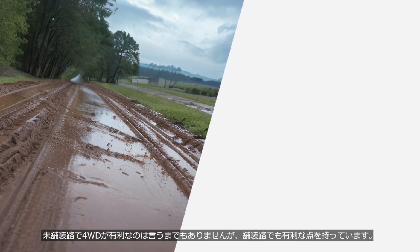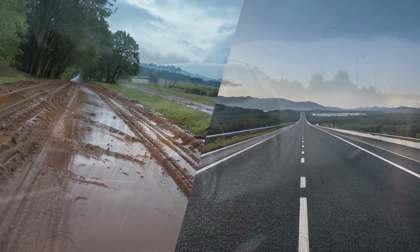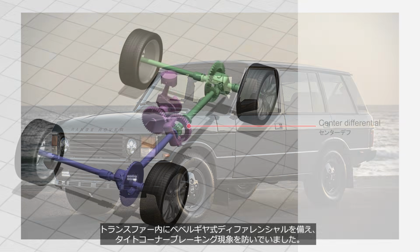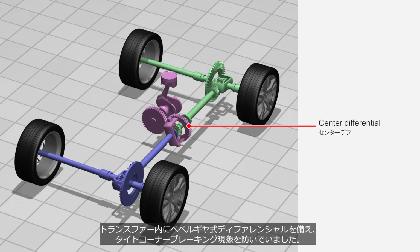While AWD is obviously advantageous on unpaved roads, it also offers advantages on paved roads. It improves straight-line stability at high speeds, and enhances stability during acceleration when the road surface becomes slippery, even on paved roads such as in rainy conditions. The first mass-produced passenger vehicle to adopt full-time AWD was the first-generation Range Rover. It featured a bevel gear differential in the transfer case, which prevented drivetrain bind during tight cornering.